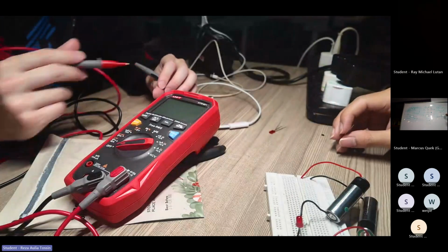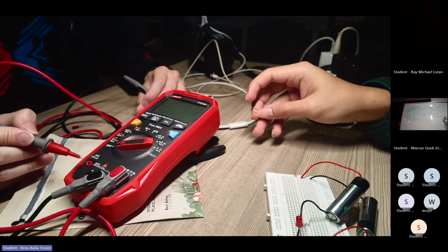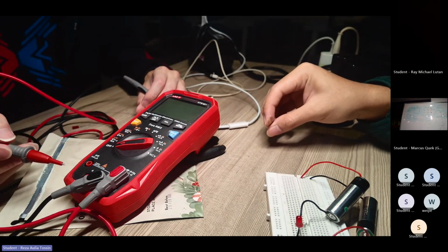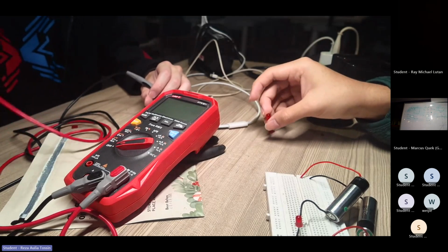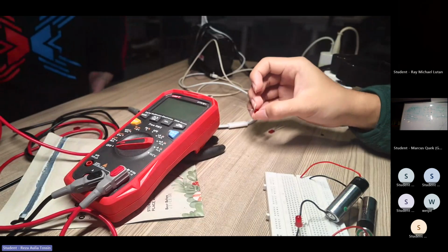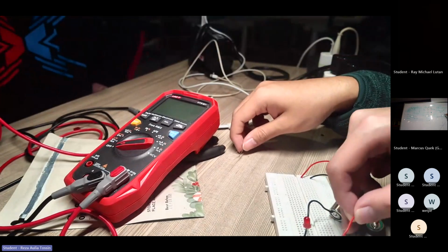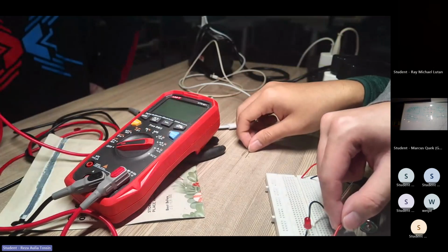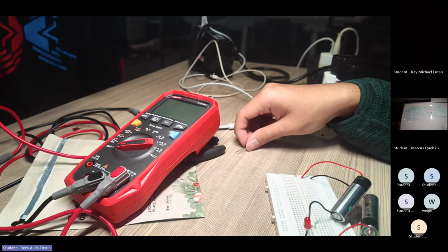What's the difference between these two poles? So this is for milliamps or microamps. This has a lower max current than this, but it's got a higher sensitivity. For this one, it's less precision, but more amps, so it takes more current to fry this one. If you fry this, you have to go in and replace the fuse, which is annoying. So essentially, if you really don't know what range your amps are in, you start with this one first. And then you see what number you get. If you see like 0.001 or something, then you change to the more sensitive one.